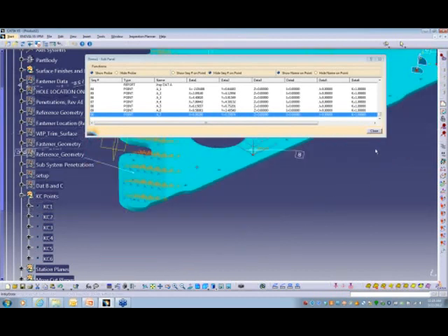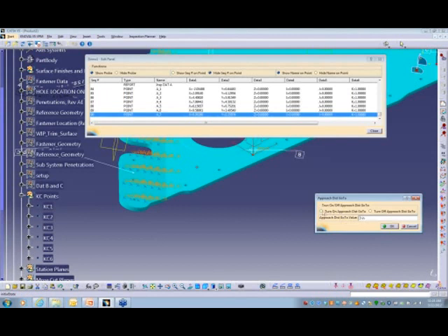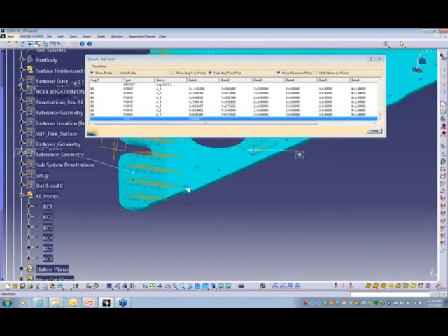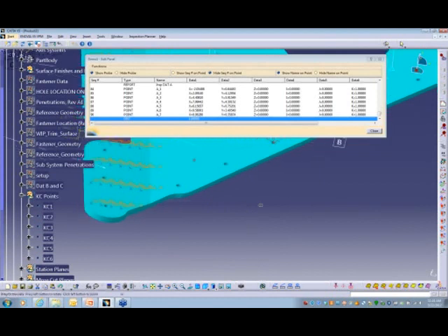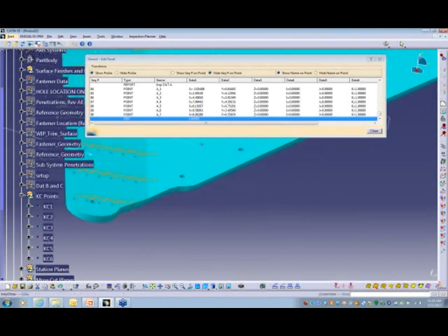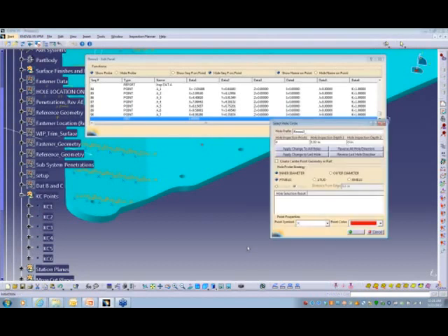I want to change a setting just so when we do our replay, everybody can see what I did. I'm going to change this setting, and I'm going to put it so you can really see the move. I'm going to put it at 1 inch. So every time it goes out of a hole, it's going to lift up to 1 inch. And let's say you might have a clamp right here. You might have some clamps, so you know by lifting up to 1 inch, you're going to be able to clear the clamps. We'll come into this hole.